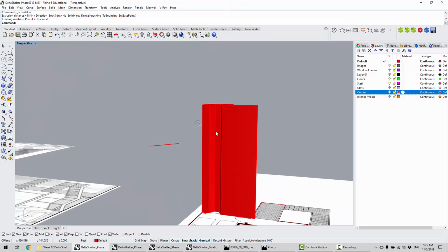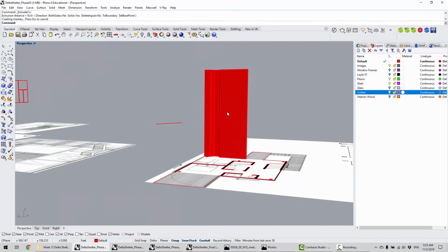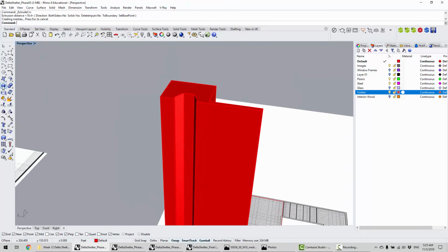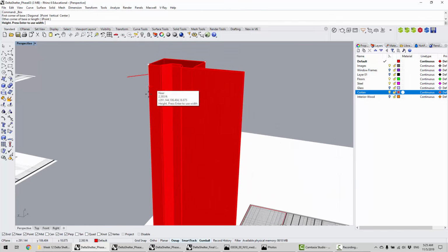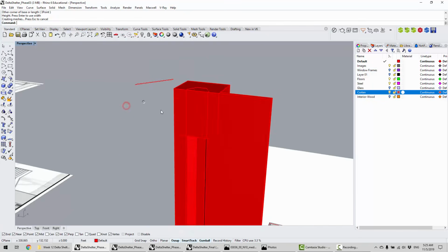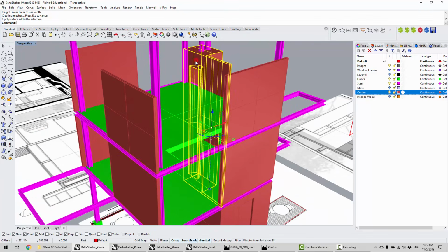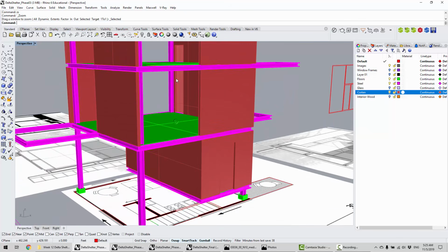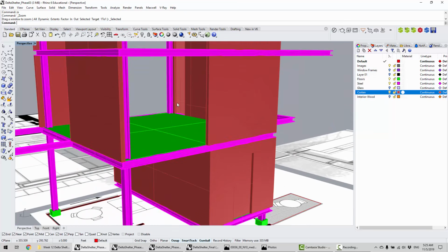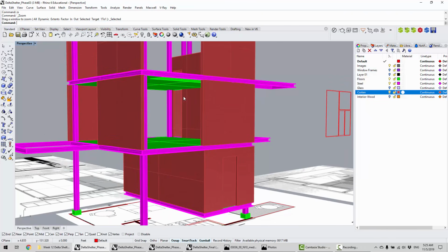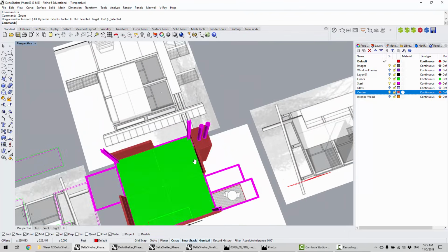The fireplace doesn't cover the entire thing. The simple fix to this is to use the box command and come down. You'll see it better in the interior of the project if you go see here. And actually, I should seal off this as well. It's really just this portion that needs to be open, this portion needs to be open, and this should be blocked off. It's not the entire wall. And you can see that in the section too.